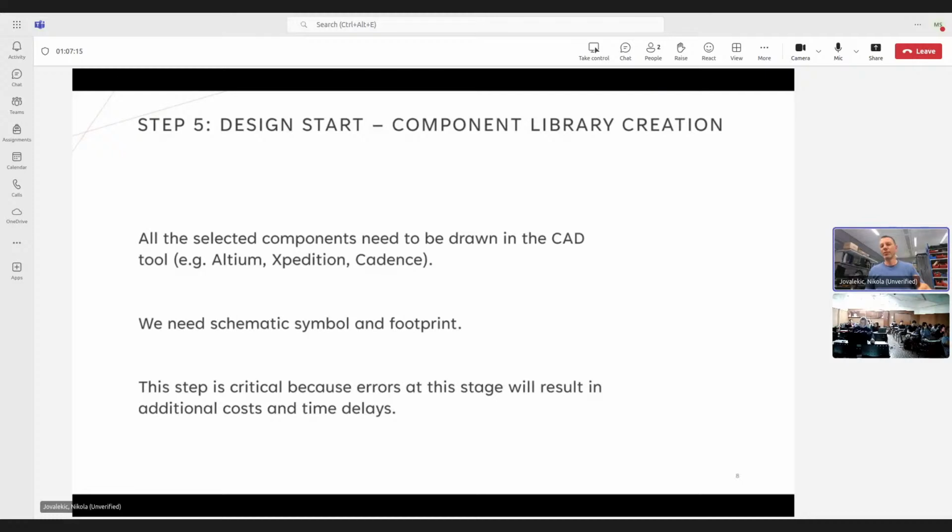Okay, so what do we do there? We do the following. We take data sheets, then we create schematic symbols, as we said. It literally means that we will need to draw this rectangle, then we need to place these pins, all the pins. We will check the pinout, or pinning, here in the data sheet. And when we enter all this information, then we will proceed to the creation of the footprint.